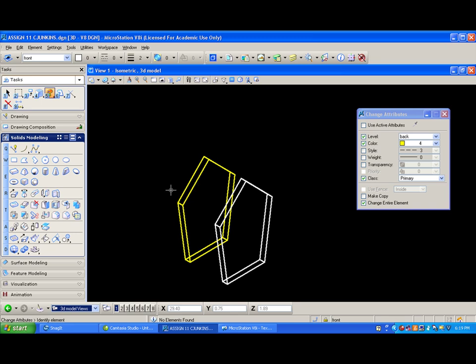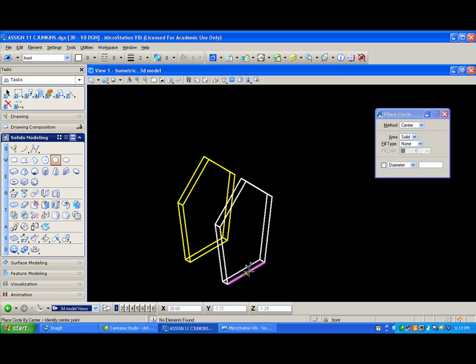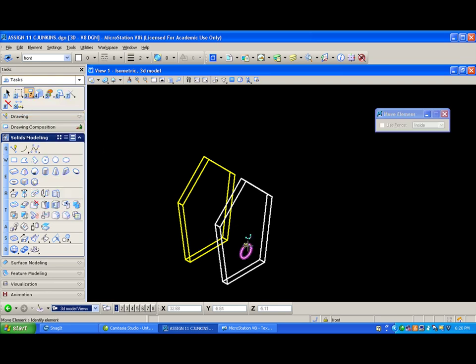Let's put a hole in this front panel while we're at it. We need to go up 3 inches, 2.5 inches for the hole. So I'm just going to left and right mouse button on the tentative point right there and hit F. And I'm going to go up a distance of 2.5. And we're going to put a hole in here that is 0.7 radius. Looks a little low, so let's pull it up another inch. That looks better. So it actually went up 3.5 inches, so 1 inch up.